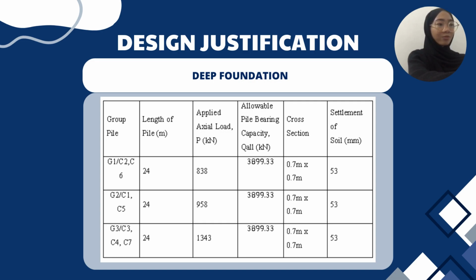However, an increase in the number of piles will increase the size of the pile cap, so the settlement of the pile group cannot be reduced. Therefore, the pile must be sufficient to bear the load applied from the superstructure and pile cap. As a result, for this deep foundation calculation, it is accepted. To justify this design, the deep foundation is appropriate to use in this undertaking, even though both shallow and deep foundations can withstand the applied axial load.